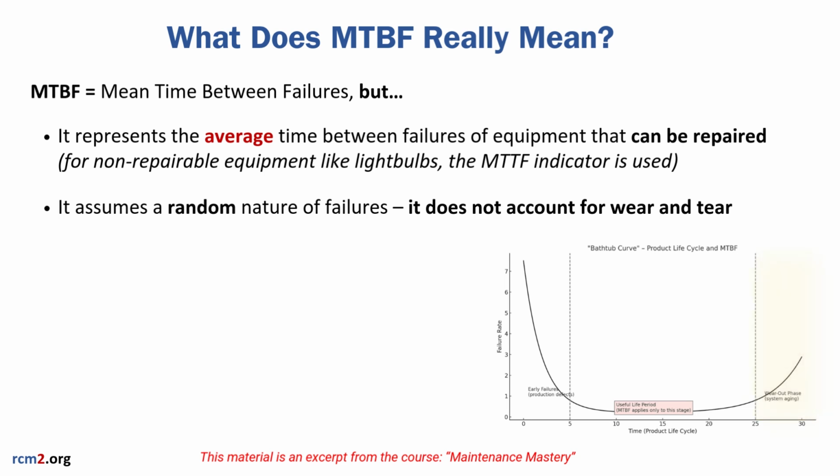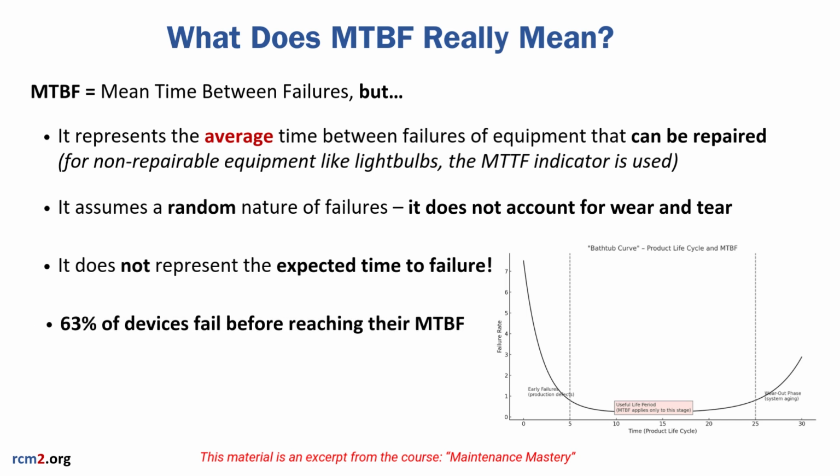It's also important to remember that MTBF does not represent the expected time to failure. In fact, statistically, about 63% of devices fail before they reach their calculated MTBF value.